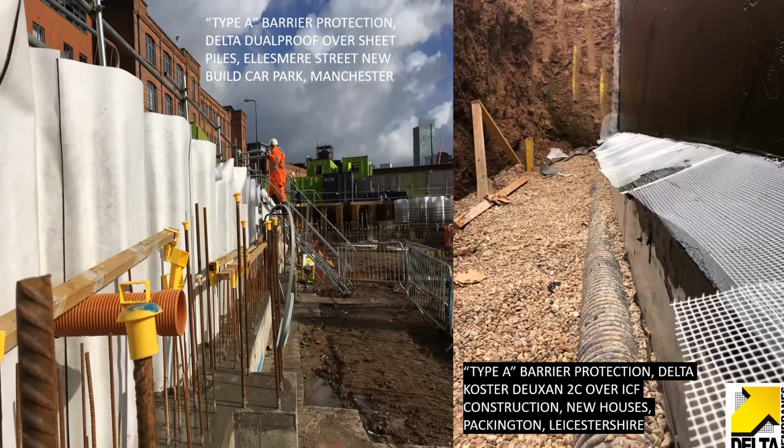The concrete will be poured up against this and it will fully bond to the concrete. This is actually a car park in Manchester on the left. On the right, we've got a type A barrier, which is a trowel applied one. It's a polymodified bitumen with some reinforcement mesh in it.